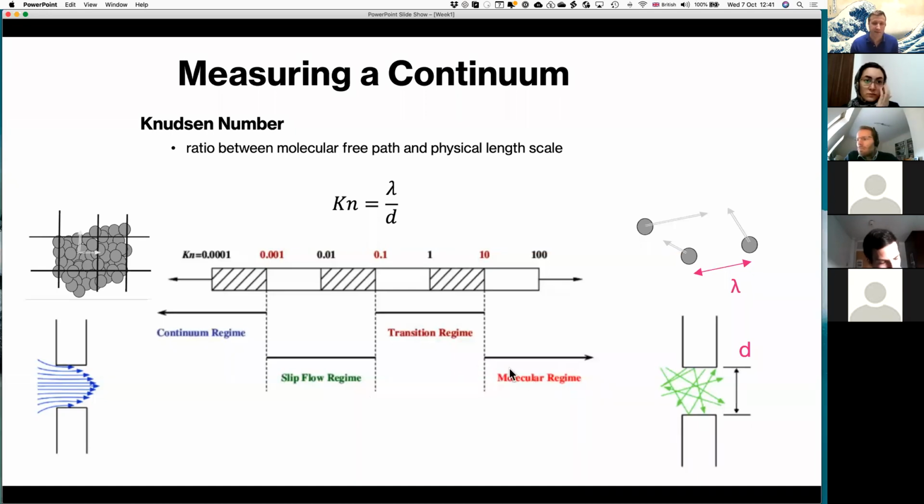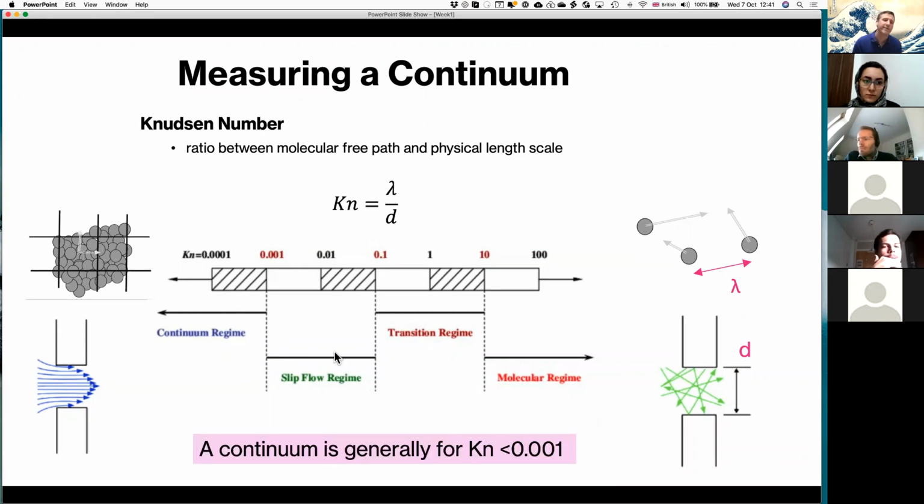And this is very important in some practical applications. As you approach a vacuum, as you're in space, then essentially you have high Knudsen numbers. But for the vast majority of engineering flows and practical flows of engineering relevance, like water and air, that we're going to be studying, you're really considering very small Knudsen numbers, where essentially we're not interested in a gap between the molecules.